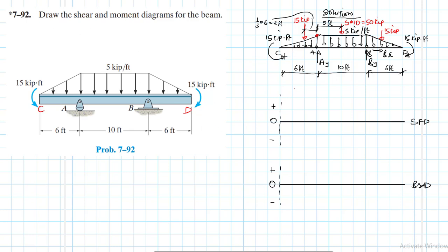So we know that at C, we don't have any concentrated load, that's where the distributed starts. And where we have distribution, in this case, the load is negative and is increasing, therefore you expect the slope for shear to also be negative and increasing, okay.